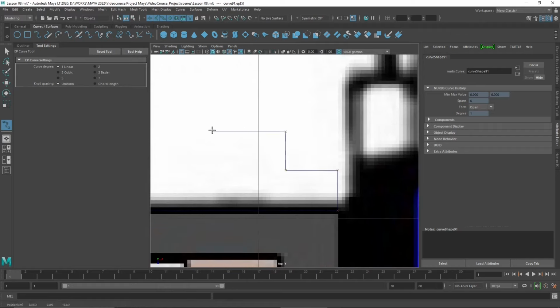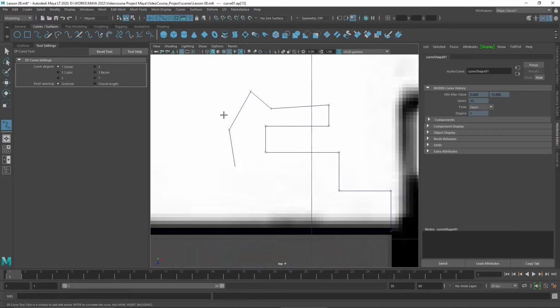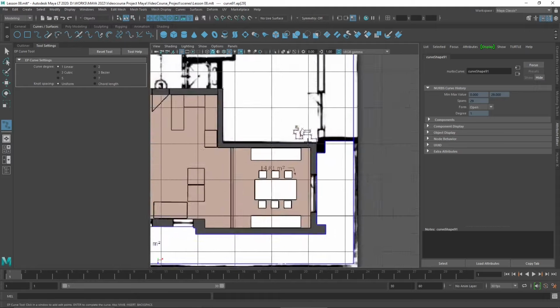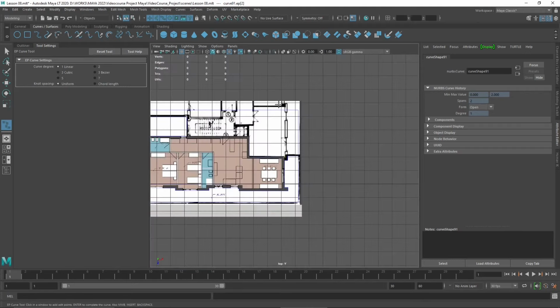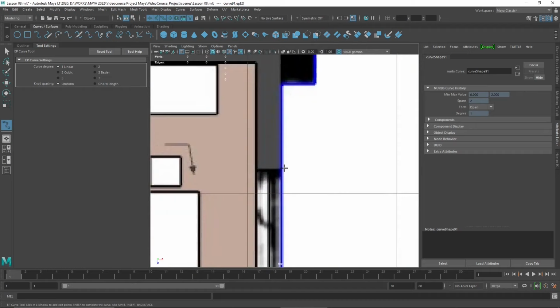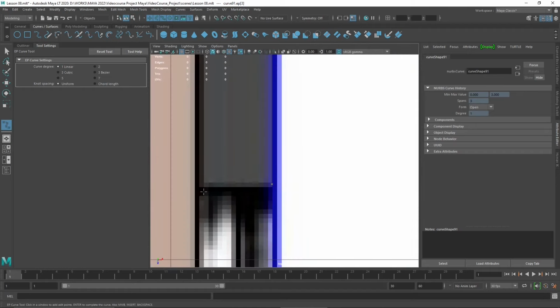Now, when you draw and you want to be precise, not create oblique curves, you can hold Shift. So if you hold the Shift key of your keyboard and continue to draw, you're going to create vertical and horizontal lines. This is also called orthogonal or ortho in AutoCAD or similar CAD applications. Now, if you want to go back because you've made some mistake, just hit the backspace key. So I'm just going back where I left off, because I went the wrong way. So I can continue to place the other points.